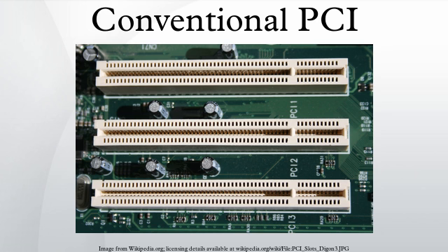The cache would watch all memory accesses, without asserting DEVSEL. If it noticed an access that might be cached, it would drive SDONE low. A coherence supporting target would avoid completing a data phase until it observed SDONE high. In the case of a write to data that was clean in the cache, the cache would only have to invalidate its copy, and would assert SDONE as soon as this was established.